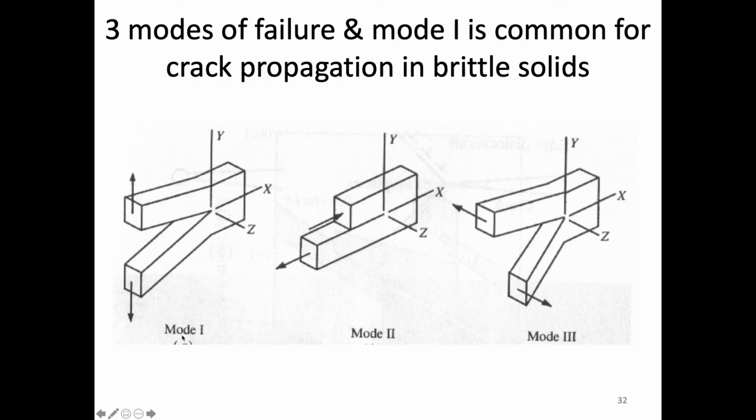Like I mentioned, there are other types of modes as well. You could have it in shear, where we have a crack and you try to shear it open. That's mode 2. Or where you try to put it in torsion, and this is mode 3. So there are different types of modes, but for our schematics and so forth, we typically just try to show mode 1.